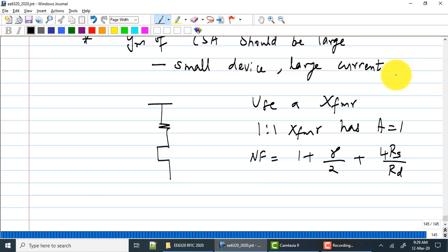In the case of a common source amplifier, you will get numbers like 1.2, 1.5, and so on, very easily because the FT of the device is so large nowadays. So you can see that the common gate structure can also give you very competitive noise figures. But by adding a transformer, you have now made the circuit relatively narrow band, because transformers are not wideband in general. Transformers in general will operate over a specific band of frequencies.